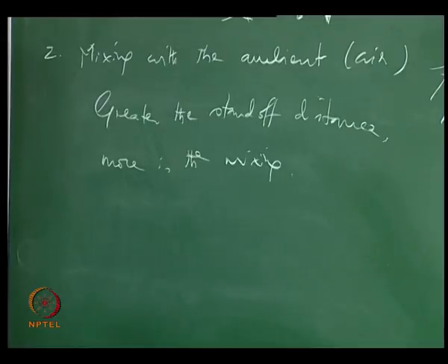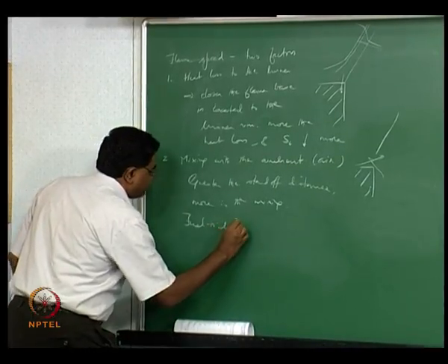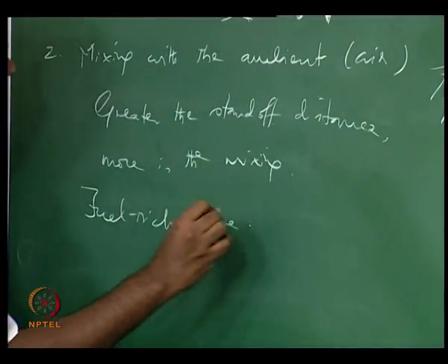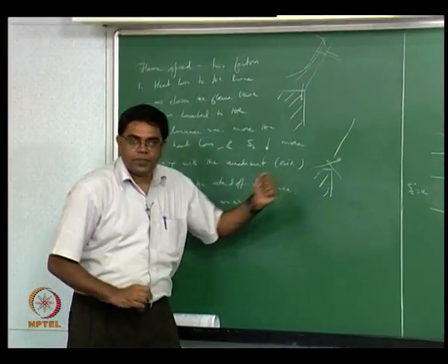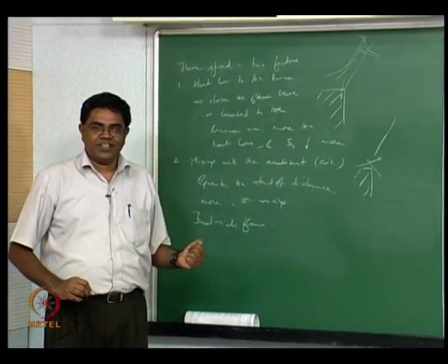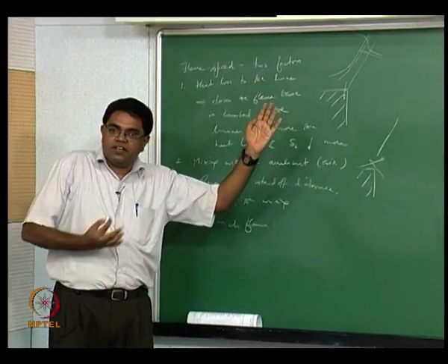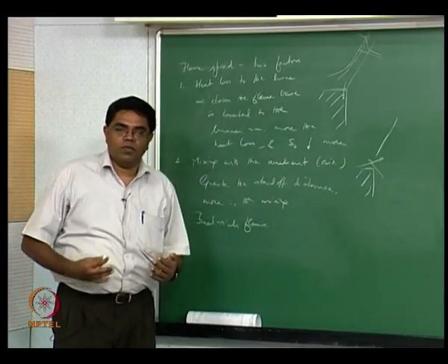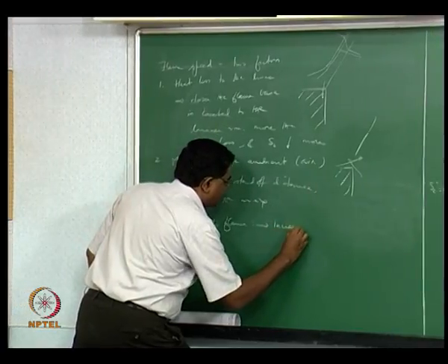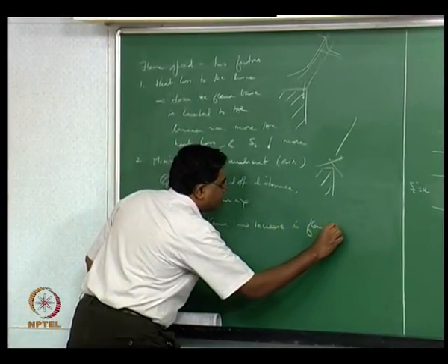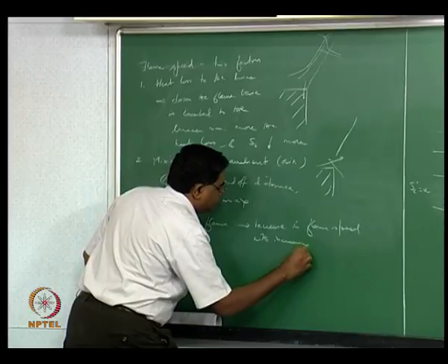That depends on whether the flame is fuel rich or fuel lean. So take a fuel rich flame in an oxidizing ambience. What happens now? This region actually becomes closer to stoichiometric, because it is a fuel rich flame and you are now sending in more oxygen from the side, and therefore it becomes closer to stoichiometric. So this leads to an increase in flame speed with increasing standoff.